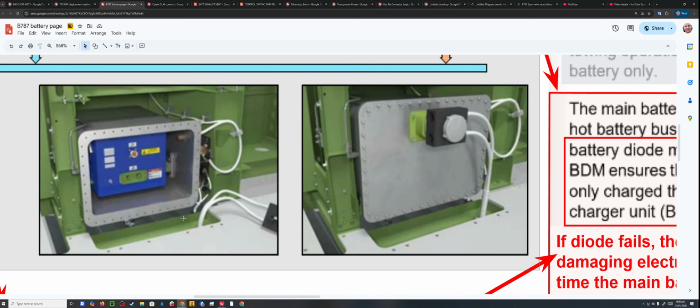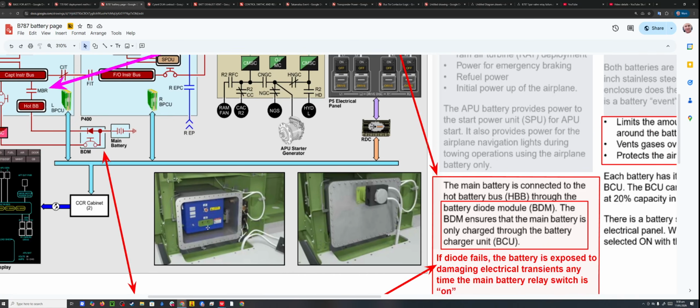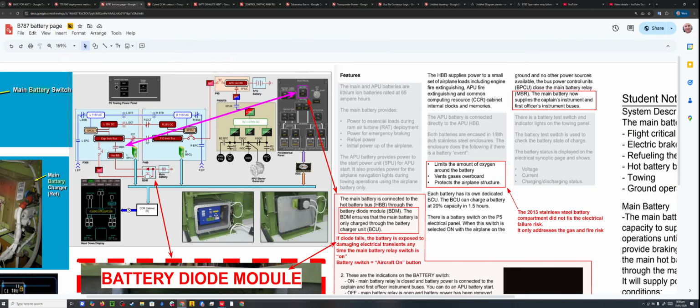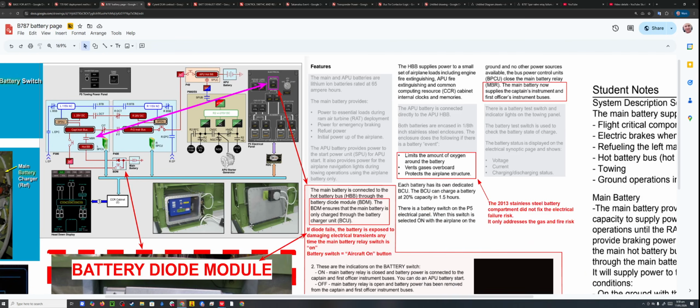And you will see from YouTuber Stig Aviation, he even complains about it in his tour of the electrical bay. He mentions that it's a pain in the ass, he says, to get to the battery. So therefore, it's very difficult to look at the battery. So if it is swelling, out of shape, or something's going wrong, you won't see it because it's inside that box. All right, and you have to undo 60 bolts. It takes him half an hour just to get into the damn thing.